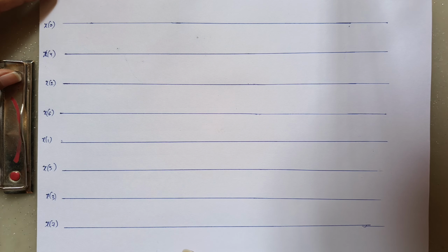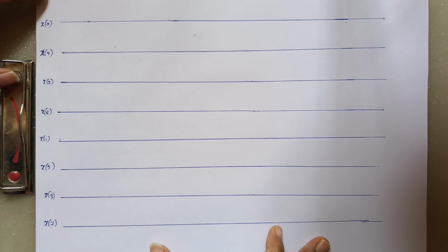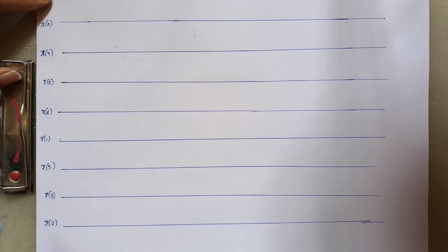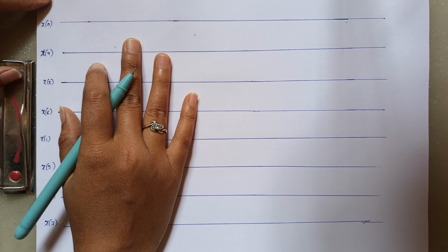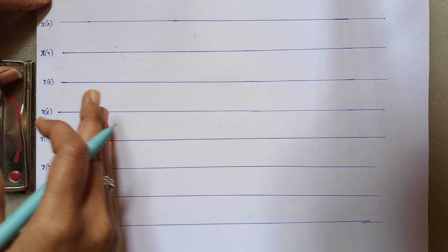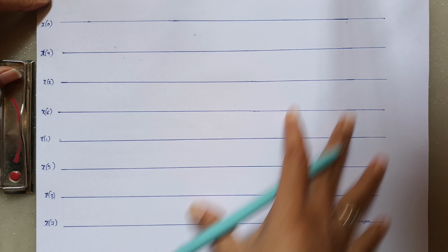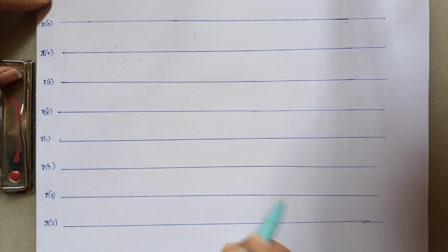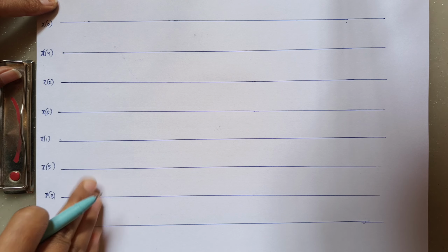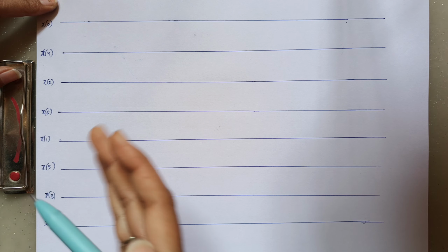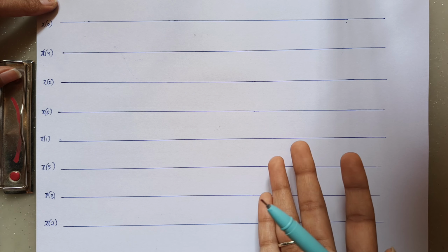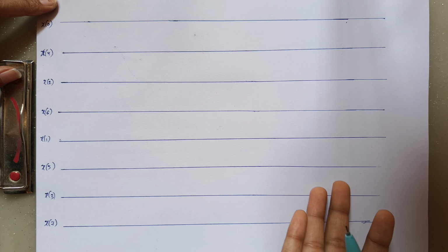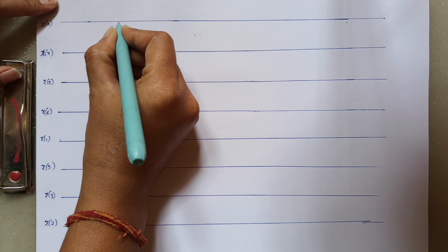So these inputs are taken in bit reversal order. So this is DIT, decimation in time. That means the input values of time domain should be in bit reversal order. Now we will draw the butterflies on this side. We will be drawing on the entire page itself, but on the left hand side we will be drawing independent butterflies, and as we move towards the right hand side we will be overlapping one butterfly on another. So I'll tell you how. First let's start on the left hand side.